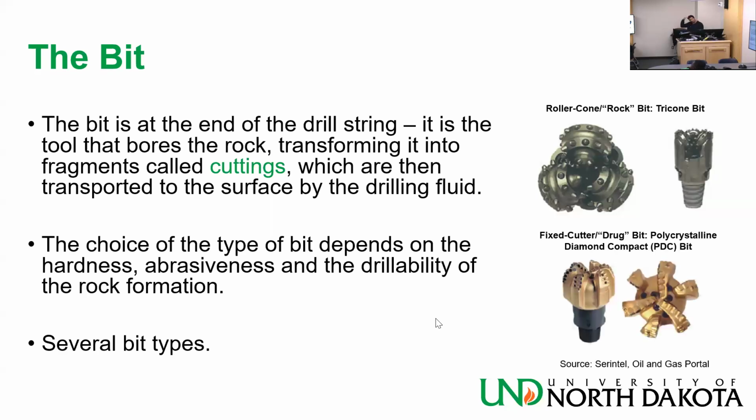The other kind is the fixed cutter bit, or the drag bit. This is again a more modern kind of bit, and it is used in different kinds of rock. If you are drilling softer rock, it might be better to use this one, but not all kinds of softer rock. Some rocks are better with a roller cone bit. Some rocks are drilled better with a drag bit.